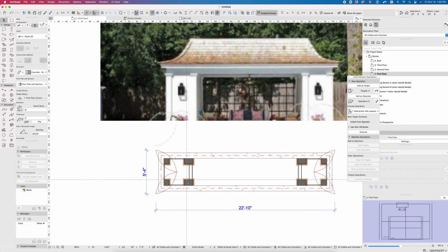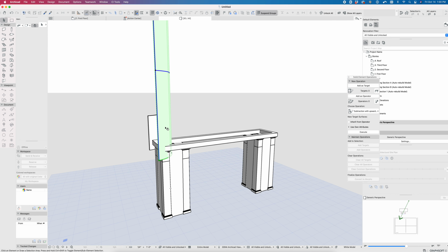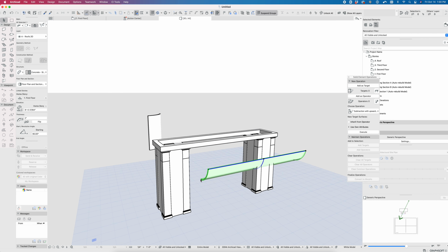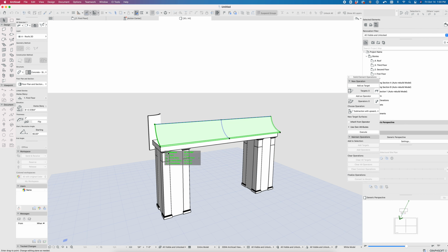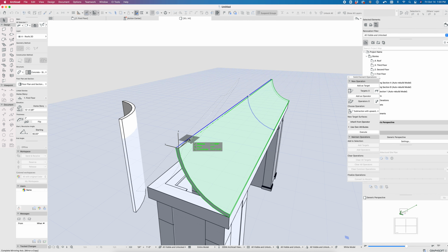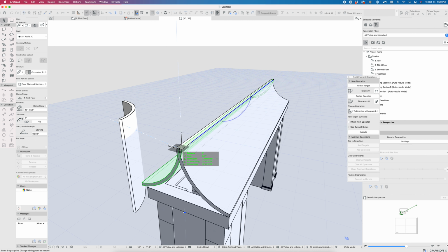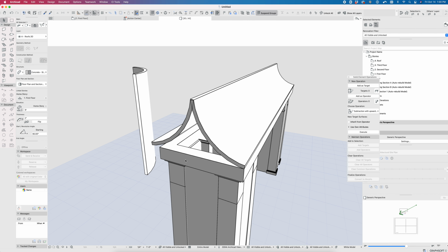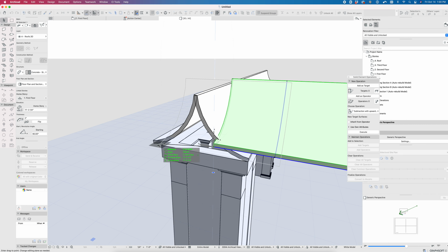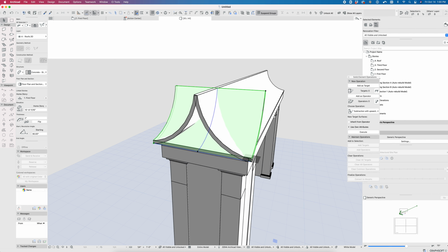Now if we look at these in 3D, I can take this one right here and rotate it horizontal, something like that. Let's mirror that so it's facing the correct direction, and we'll put that there. We can mirror this right over the top of itself. Then we'll rotate this one also to be horizontal. The extrusions are always vertical, so we do have to fuss with that to get it to work out correctly. It looks like I'm a little bit long on that,